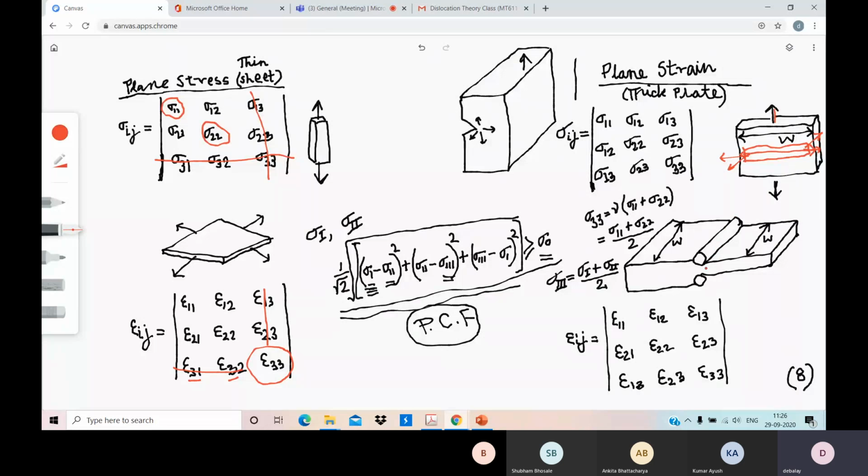Similarly, when we do rolling, when you deform a particular volume of material under the roll, its height decreases and its length increases, but it also likes to extend in its width, because the excess metal has to reduce its height and the excess metal has to elongate the length and elongate the width. But the width elongation will be resisted by the part of undeformed metal, which will apply a constraint. So you will find there is no change in width. And that is called plane strain.